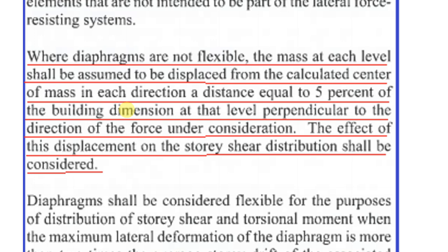at each level shall be assumed to be displaced from the calculated center of mass in each direction a distance equal to 5% of the building dimension.